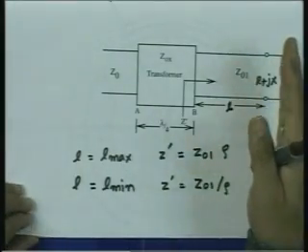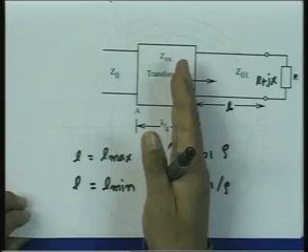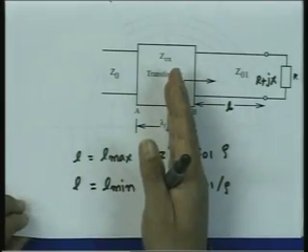So realizing any arbitrary value of characteristic impedance is not very easy. So though principally any complex impedance can be matched to the characteristic impedance by using a quarter wavelength transformer, in practice it finds difficulty, because it will be difficult to get a separate transmission line for each impedance matching which is to be carried out in the circuit.